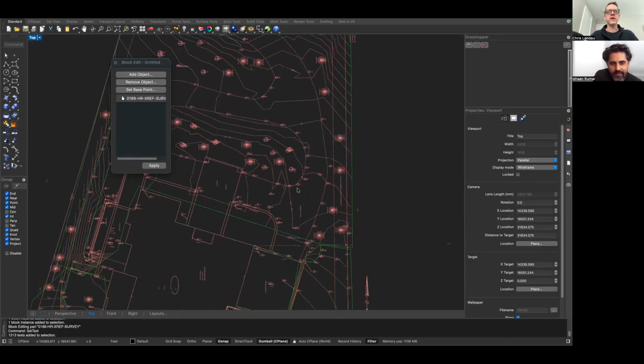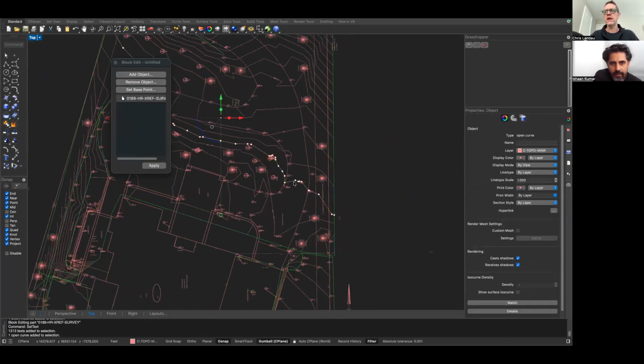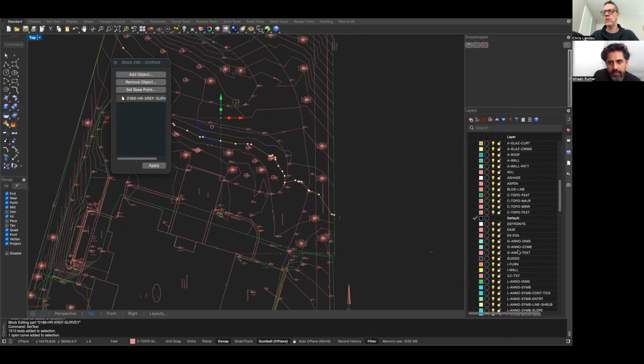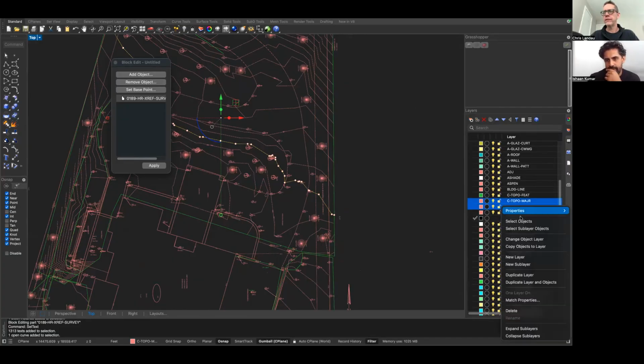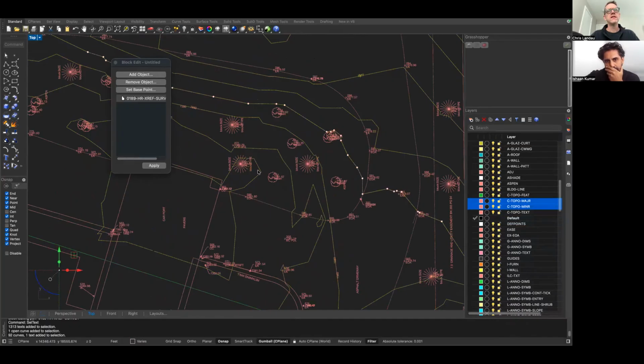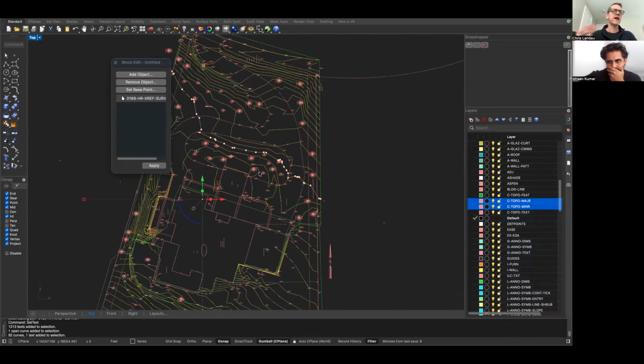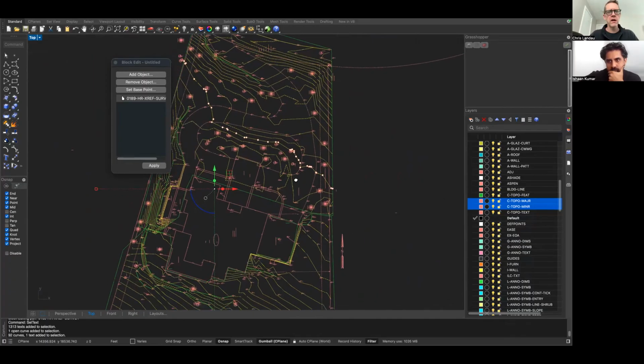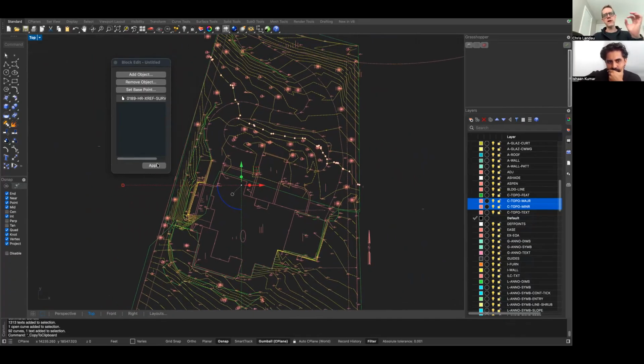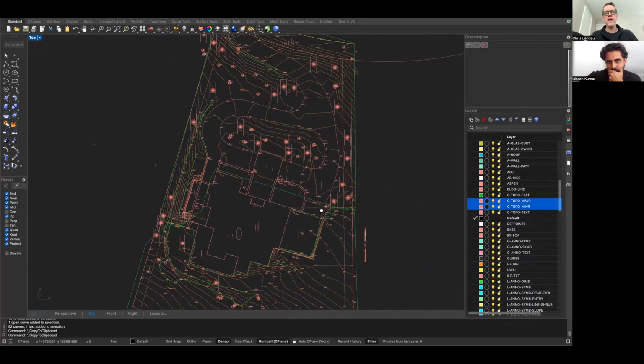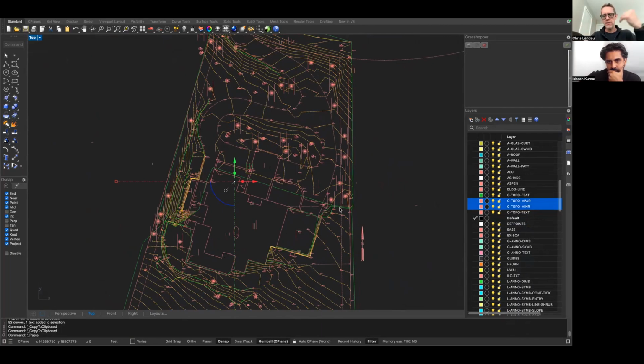The other thing I want to do that's really important is select all my contours, right? It looks like we have the topo, major and minor. There you go. We'll select those objects. Sometimes people will also have their annotations on that layer, and sometimes there's a little bit of sorting. But I'm inside of the block right now, so I'm going to copy these elements from that area and say apply, and then paste them back into the main file after I close the block.